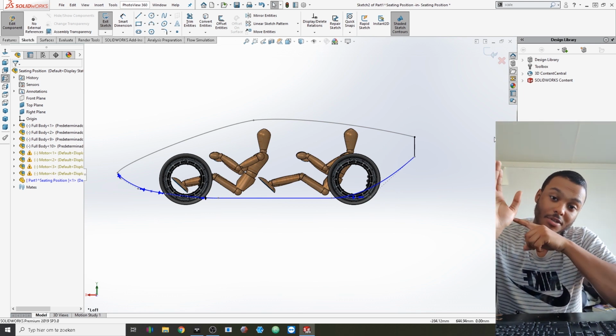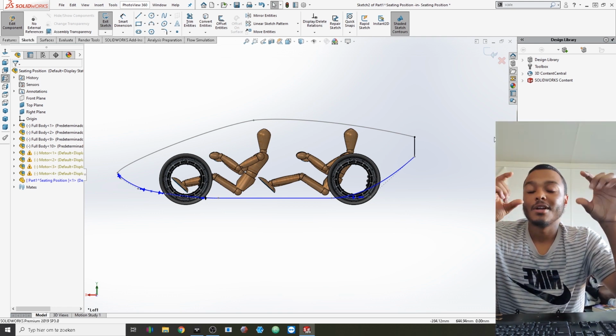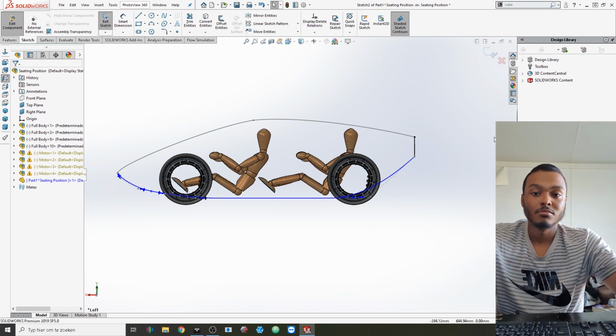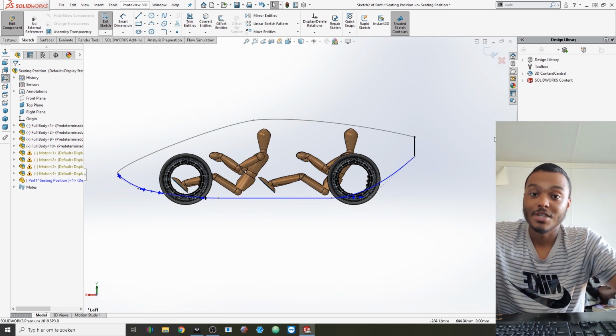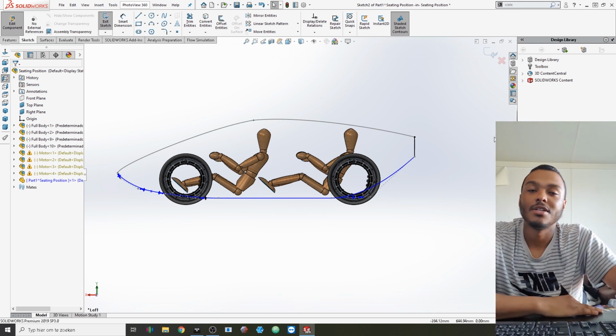So by giving the bottom of the car a similar curvature to the top, you can eliminate that speed differential in air currents from top to bottom, creating less lift on the car. That would inherently help with creating downforce, because it is close to the ground, so you will have ground effects, and then you will create downforce.